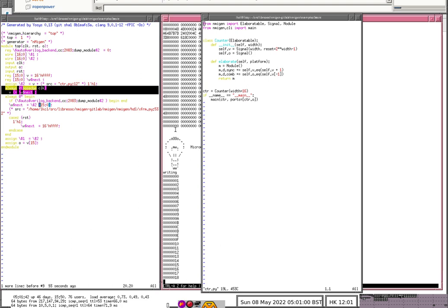Yeah, okay, so we're getting there. But this is fairly standard practice. If you handwrite Verilog, you do your next signals combinatorially, and then you put an explicit always on the clock's rising or falling edge and do the assignment. So this is pretty much standard practice. It just took a little while for me to work it out.